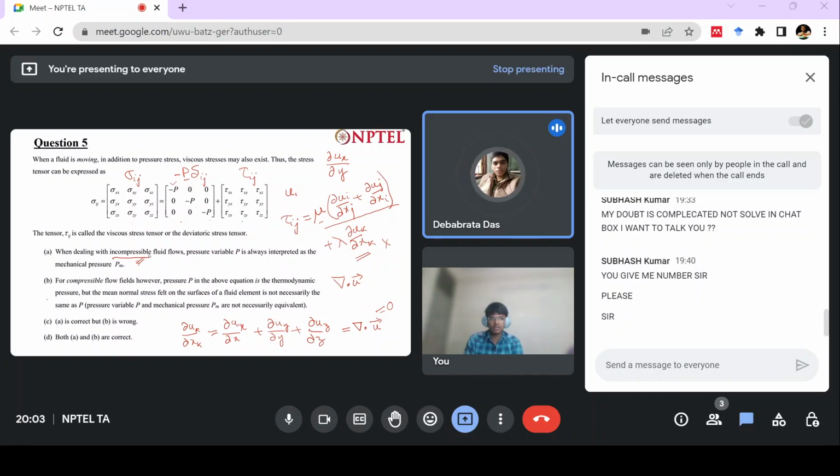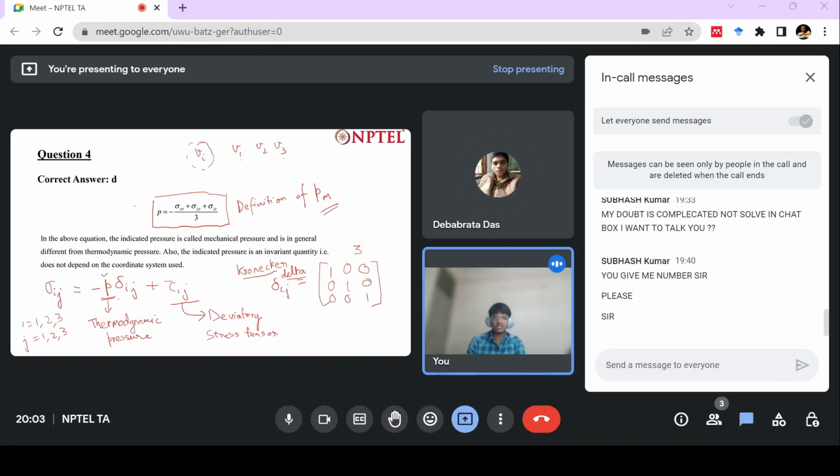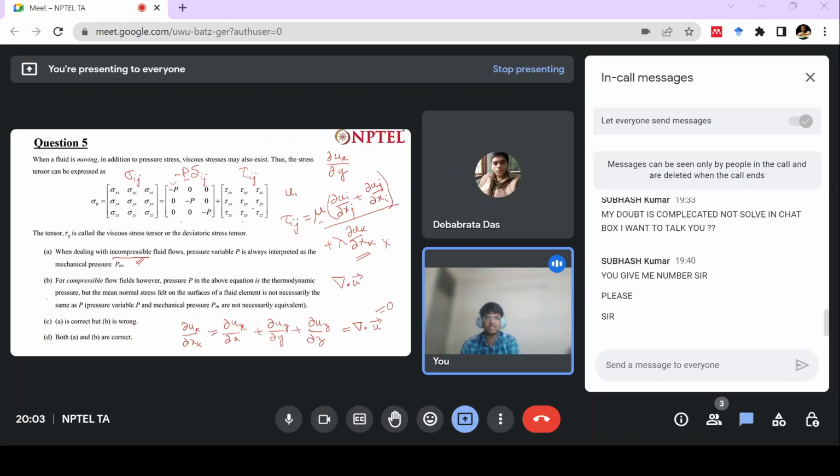Yes, sir. If that is the case, then your normal stresses, however you define mechanical pressure, you define it using your normal stresses, right? Sigma xx, sigma yy, sigma zz. If you do that same thing here, tau xx plus tau yy plus tau zz, you will see that you'll only get this pressure P. So sigma xx plus sigma yy plus sigma zz will have this pressure component.